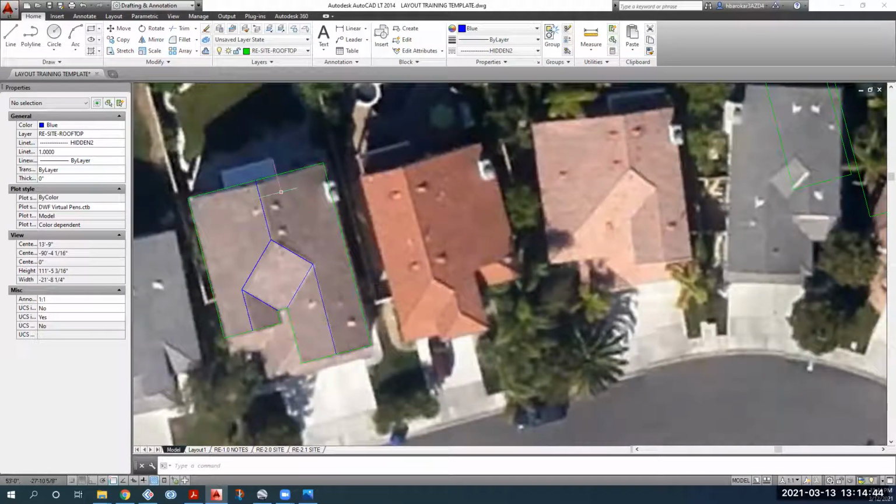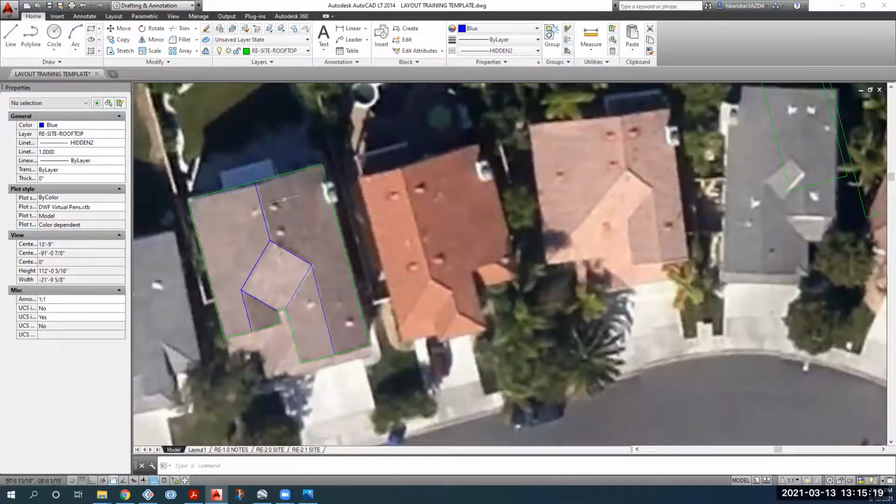Now we are going to move to the next part, which is drawing the details, okay? The details means the chimney, the obstructions, the little vents and all the little pipes that stick out of the roof, all the plumbing work. Sometimes it's just air conditioning work. Sometimes there are pipes. Sometimes there are TV dishes. We need to get all of those in this layer called details, so that we positively identify them at the time of our drawing, and later when we are trying to make the model, we have already accounted for their shade as well.